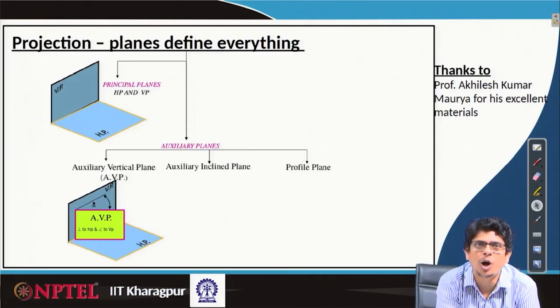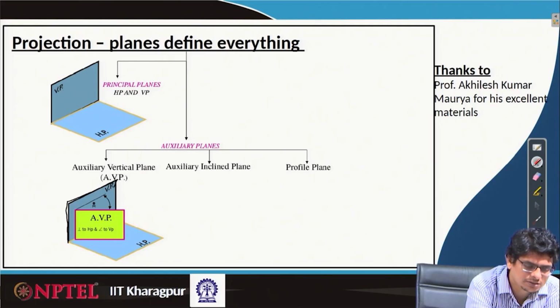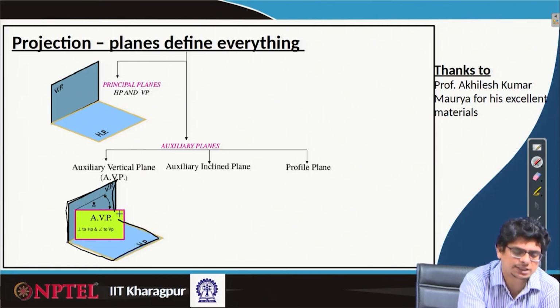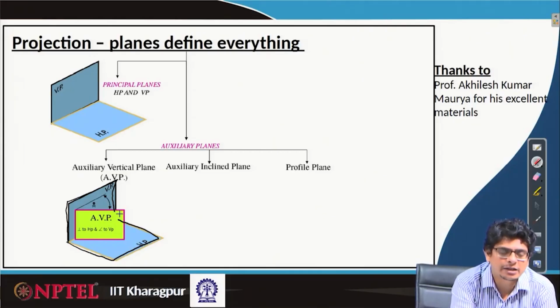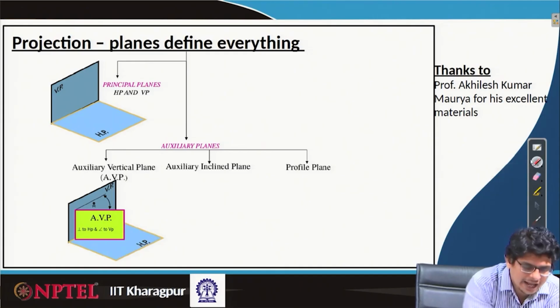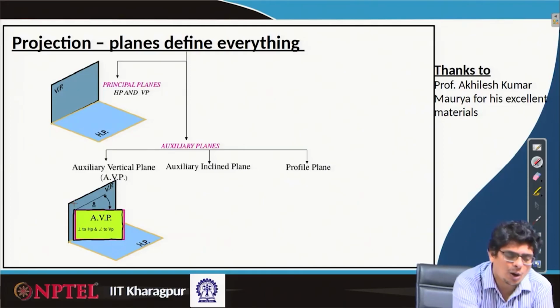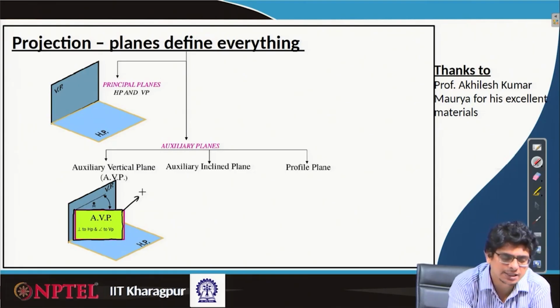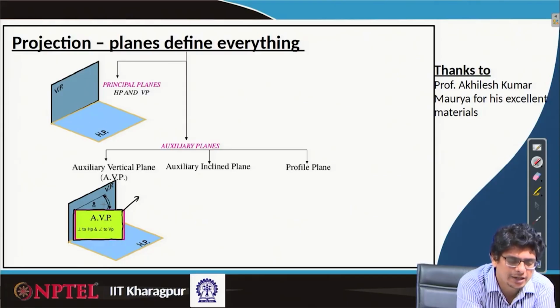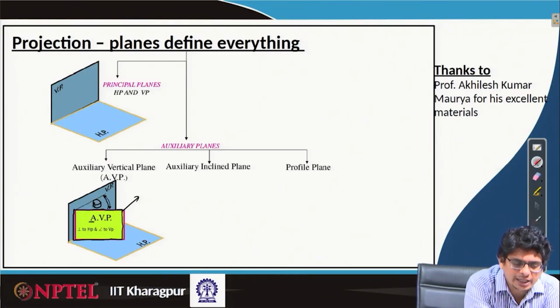For example, let us look at these auxiliary planes. So, the horizontal and vertical planes, the vertical one and the horizontal one, are always fixed. Now, we would like to take any other plane inclined either with the vertical plane or the horizontal plane. Let us pick such a plane as this one, the one which is shown in magenta color. This auxiliary plane is also in the vertical direction, vertical to the horizontal base. However, it is inclined to the vertical plane by a certain angle, some theta. If we look at more details, this auxiliary vertical plane is perpendicular to the horizontal plane.